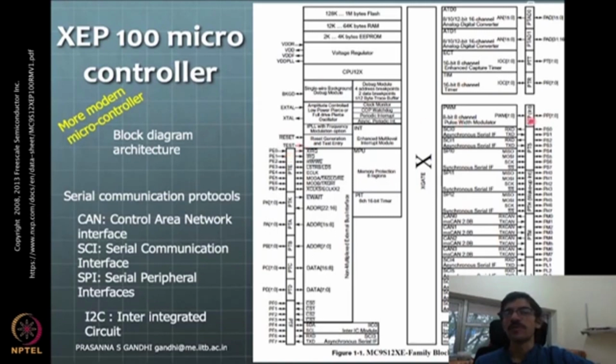So for example, if you want to say, can I have 20 analog sensors interfaced with my microcontroller? How do you answer this question? Think about this. I want to interface 20 sensors, which are producing analog output, with this microcontroller. Is it possible? By looking at this diagram, you need to look at where you'll give this analog input. You'll give this analog input to the A to D converters here. So this is a 16 channel A to D conversion.